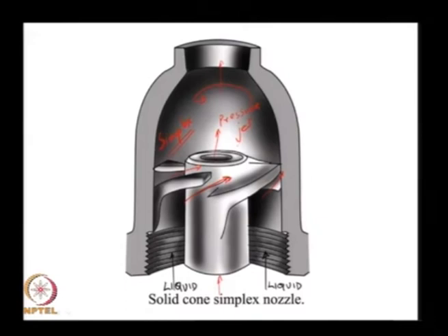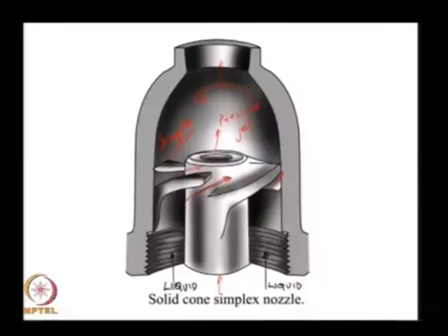So, while I have ensured that there is a more uniform drop volume distribution, that drop volume in the middle of the spray near the center line of this spray is going to be distributed into larger drops in comparison with the drops on the periphery of the spray. So, this is sort of a byproduct of this kind of design. There is really no way around it as far as this design is concerned. Okay, but we have at least overcome the problem of having nothing in the middle, no fuel or no liquid in the middle.